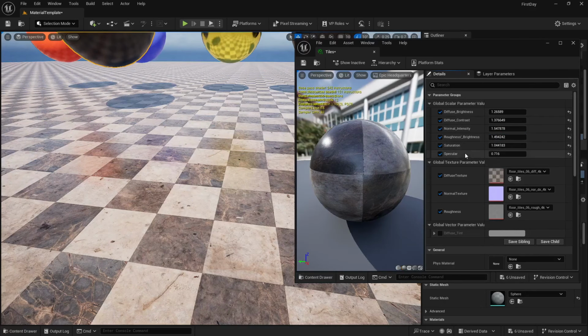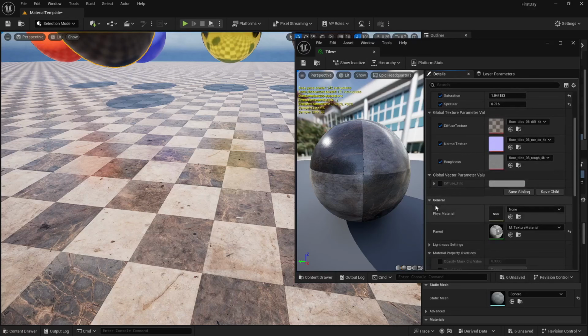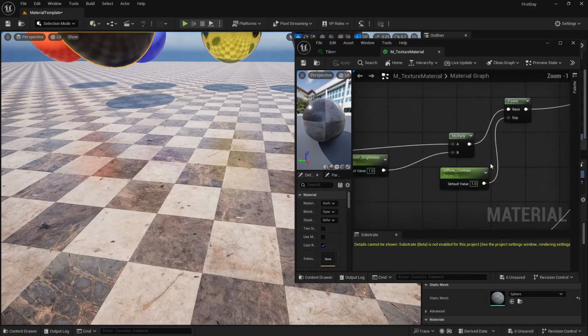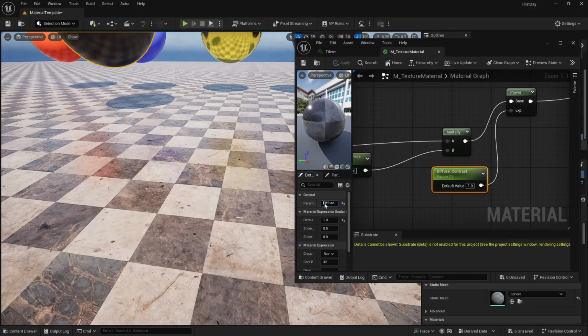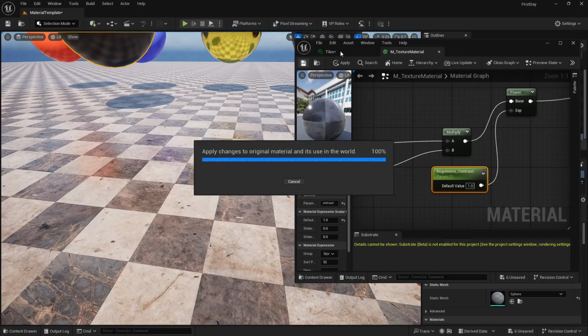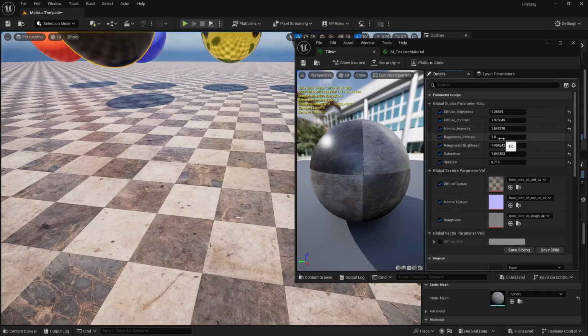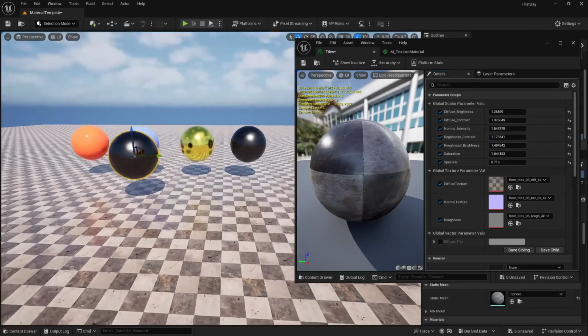And now what we can do, we can also have the roughness contrast as well, which is here somewhere. So where is our roughness, brightness? Yeah, diffuse contrast. We need to rename this to roughness contrast. Okay, roughness. This is done. Let's just save this here. And if I go here, now you have the tab of roughness contrast, and we can play with the contrast values of the roughness. See, this is a really good thing. Now you can control each and every material.